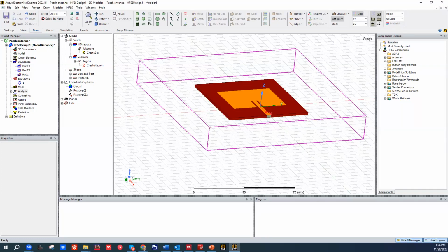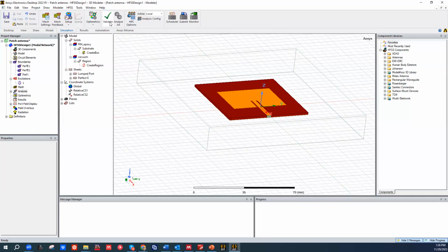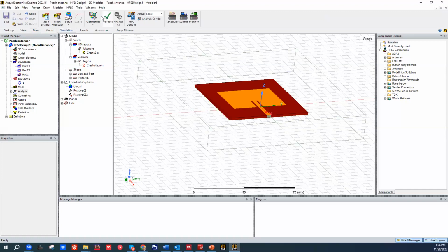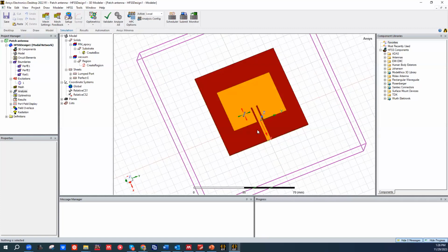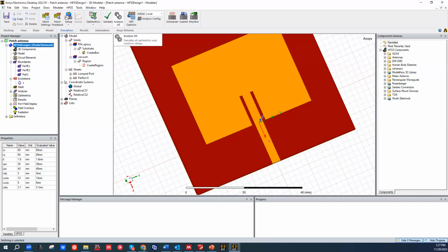All right, so we have project, we have boundaries, we have basically all set, and now we can first validate the project. So all these check marks are green, and we can go and simulate our antenna. So for now we get these cuts of the length of 5 millimeters. So let's simulate our antenna with these particular cuts.